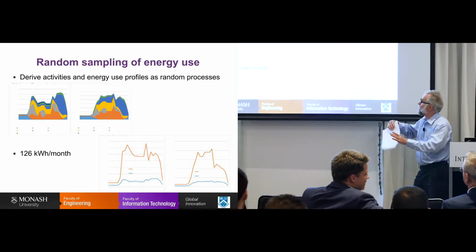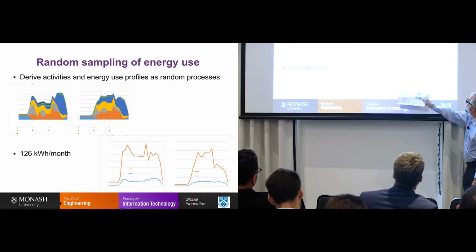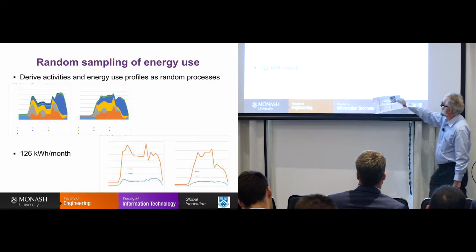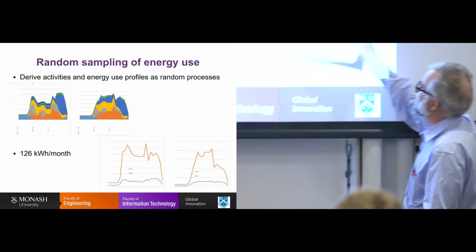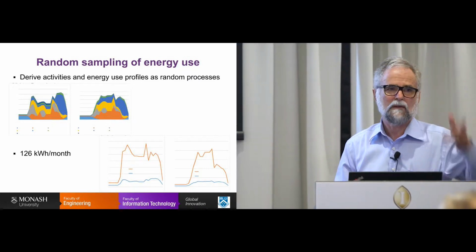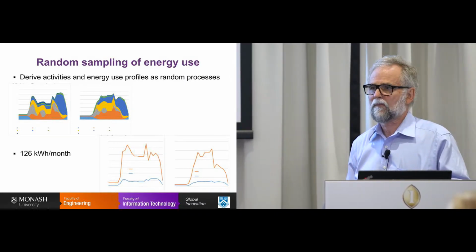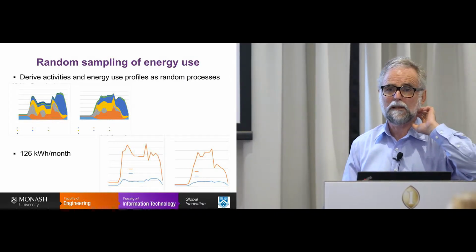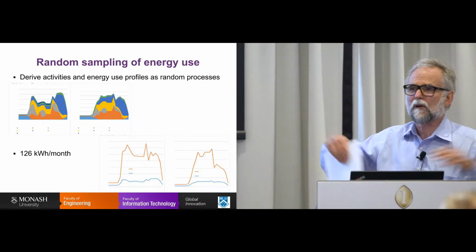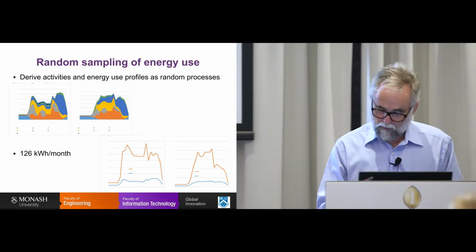When I then modelled all the appliances, that built up an average load profile on the work day and the non-work day. Interestingly, it's a bit flatter on the non-work day, with a maximum peak potential for the time of day. As you know, domestic load profiles are very volatile, and the peak load is up to 5 to 10 times higher than the average load at any time. Of course, when you put hundreds of thousands of domestic profiles together, it's all a lot more stable. But this represents the full stochastics, which is important if you're only trying to model one profile.